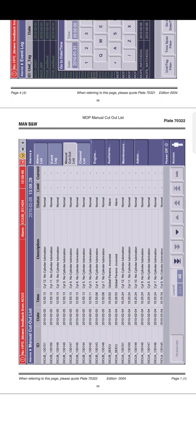For example, a tacho pickup is failing, the engine is running on the redundant tacho system and is continuously giving an alarm. In that case, you cannot replace the failed tacho system immediately. Suppose you manually cut it out and continue to operate the engine, so this will come in the manual cutout list.